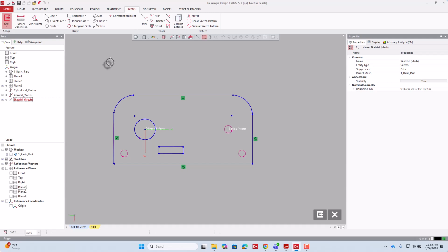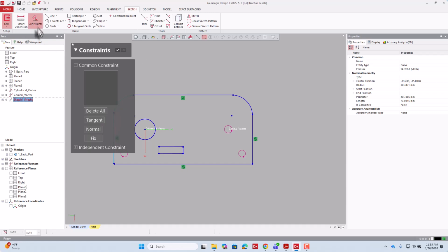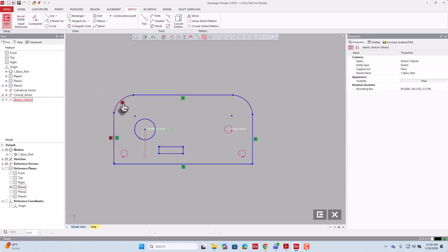You can also use this method to add other types of constraints. So you can say, hold this line, click on line 1, and then select this arc as well. Click Select. Now both of them are selected. I selected line 1 here. Click. Now here I am holding Shift or Control and then making another left click. I selected both of them. So I can go to Constraints and say make them tangent. So this is going to apply a tangential constraint between this line and this arc.